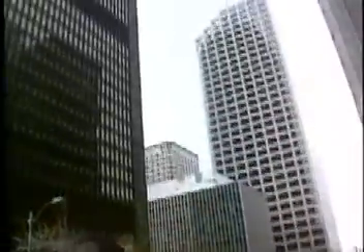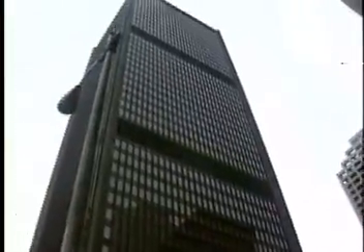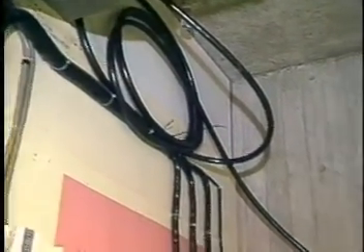When working in buildings, it is best to work from the top down, since vertical cable pathways tend to become more congested on the lower floors. By pulling cable down from the top floors, it will be exposed to less friction during the majority of the pull. On each floor, a generous amount of slack cable is looped at the correct bend radius and stored for use in the cross-connect panel.